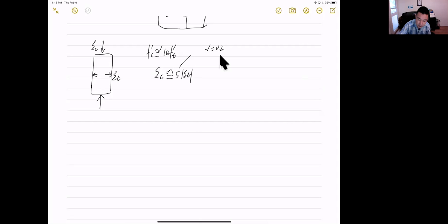So around 5 times the strain in the tension direction. And if we assume the concrete is purely elastic and the E value in all directions remains the same, then we can conclude the stress under compression will be around 5 times the stress under tension.